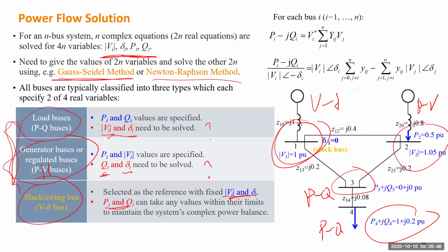Okay, so then this power flow problem can be solved. If you ask about any other type of buses, yes, you can definitely define other types. If you have some new device which may be able to control, for instance, power and angle, or maybe the reactive power and angle. Reactive power can be controlled by a controller. Angle may utilize a control system called a phase lock loop, which can track the angle of that area and adjust the angle.